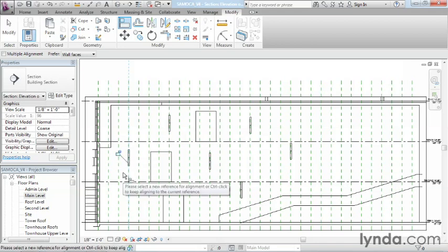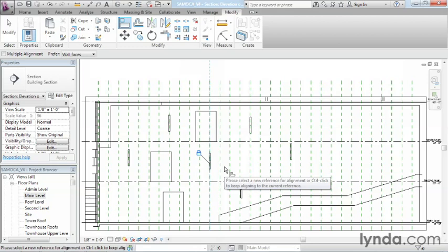You can even lock those if you want to. The advantage of locking them is if you anticipate changing the spacing of the reference planes, like I showed you a few moments ago. So if you're not settled on the 5-foot spacing yet, and you want to try varying it around, then it would be a good idea to lock these. Align it, lock it, align it, lock it. When I did this, sometimes I used dimensions to set the vertical. Sometimes I just eyeballed where I wanted them vertically. You can get as detailed with this as you want to get.